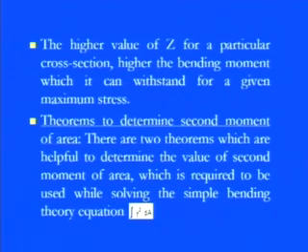It is not a simple, linearly varying uniform structure where we can put the integration from 0 to some value and get the result. Here we have a non-uniform section in which different segments are there. So it is not easy to get all those small segment areas, the y squared dA, and then sum them. Here we need to go with certain theorems.